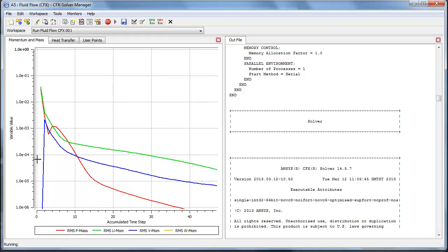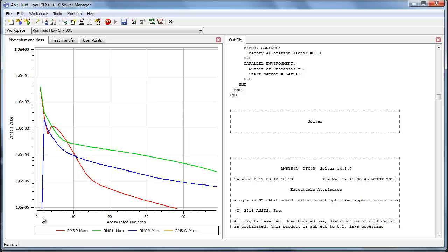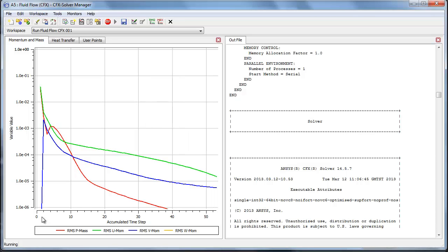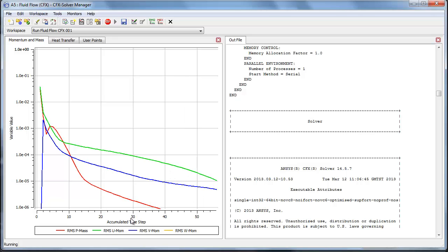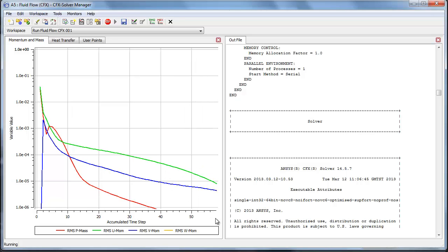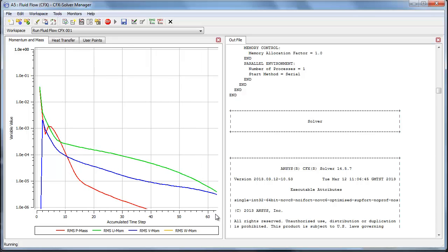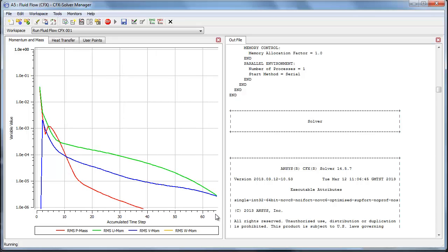The z direction is dropped off since this is a 2D problem. There's essentially nothing to solve in the z direction. And I'm watching the residuals as I go from one fake time step to the next, so you can think of this as an iteration in the solution process.